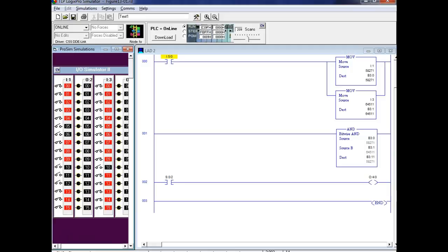Microprocessors support what they call add with carry. When you do that, what do you do for the sign? Well, if you were doing 64-bit math, then you would check the second group for your sign, not your first group. Does that make sense?